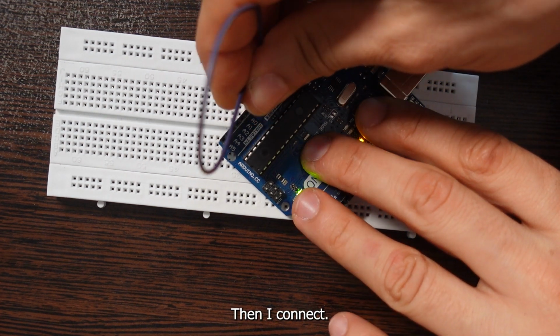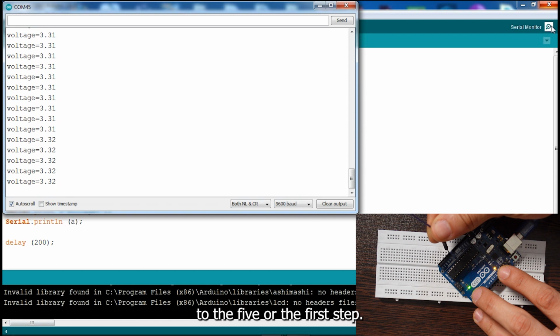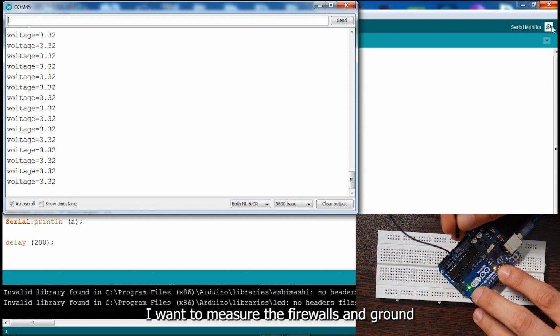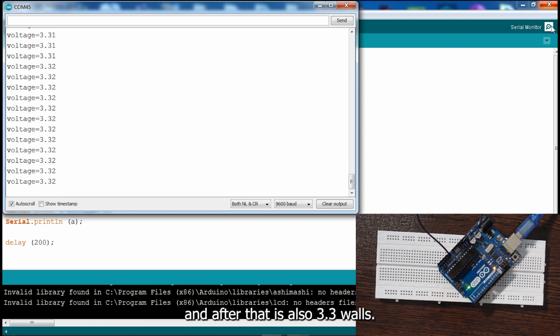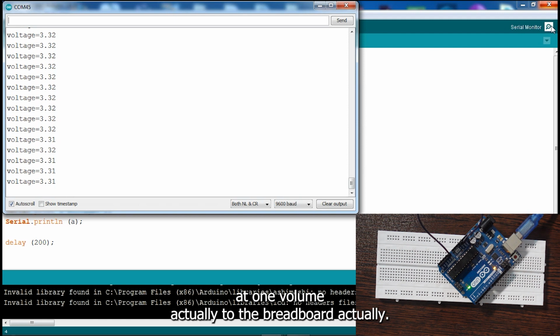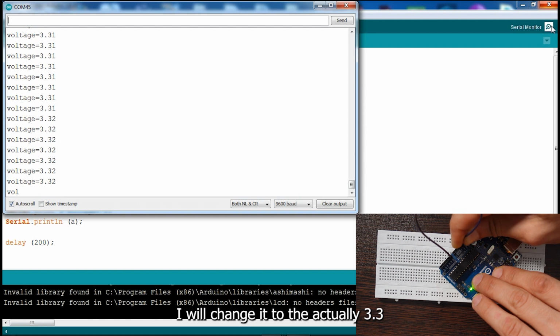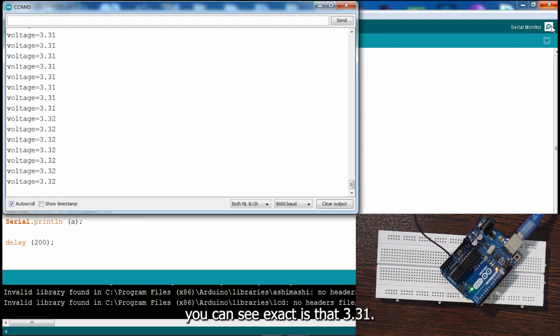Then I must connect the A0 to the 5 volts. For the first step I want to measure 5 volts and ground, and after that also 3.3 volts, and after that I will connect one volume to the breadboard. So now as you can see, voltage is equal to 5. I will change it to 3.3. You can see it is exactly 3.31.